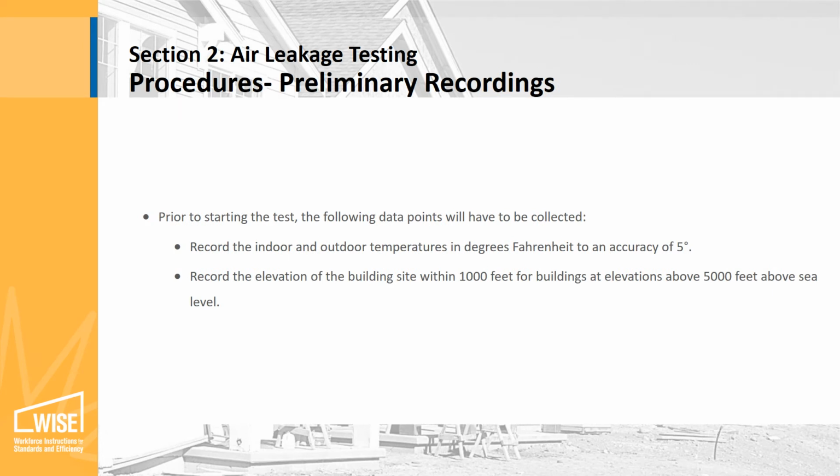Prior to starting the test, you will need to document the indoor and outdoor ambient temperatures in 5-degree increments. If the building is at an elevation greater than 5,000 feet above sea level, record the elevation.